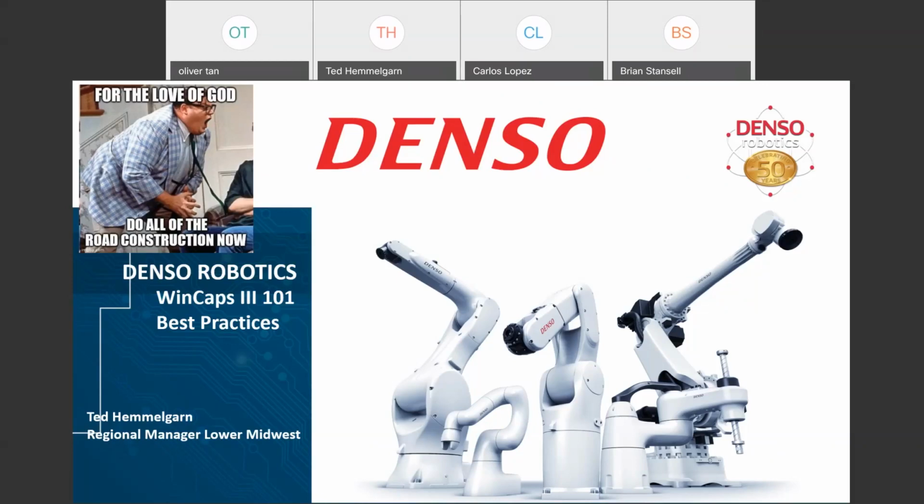Mark asked, what cameras can be used with this version? Table from Excel. So, what cameras can be used with Vision? Pretty much any Vision camera can be used with our controller. We just need to get communication with their Vision camera and set those variables for the XYZ, rotation XYZ, and send it to our robot.